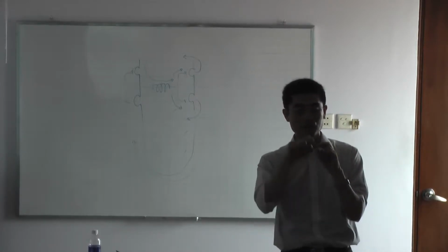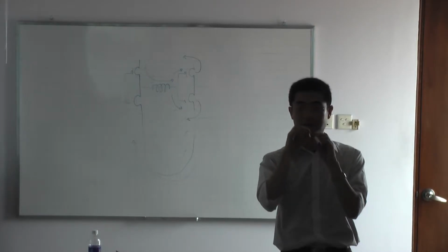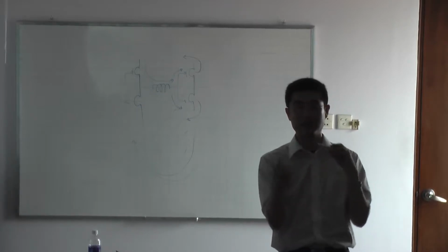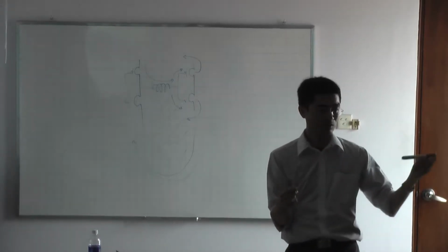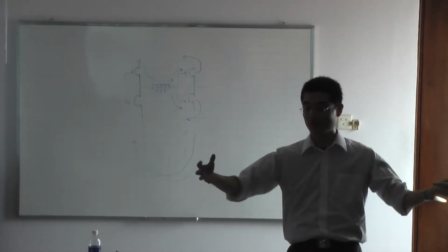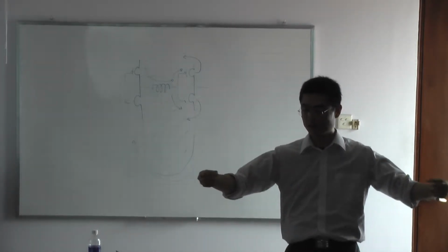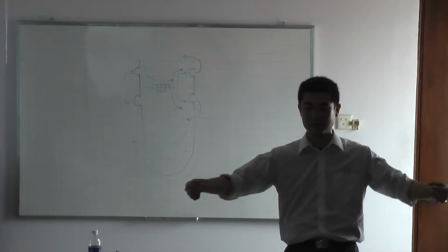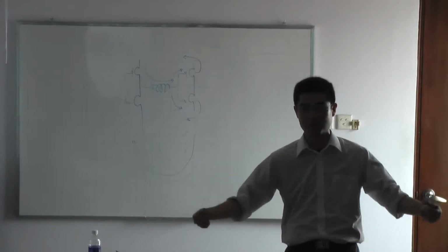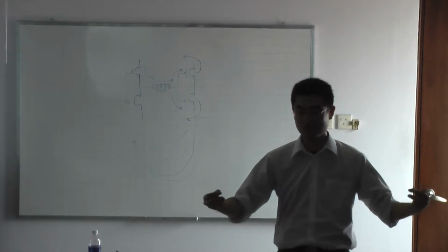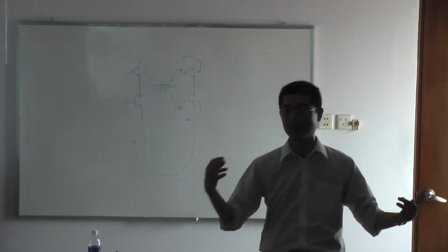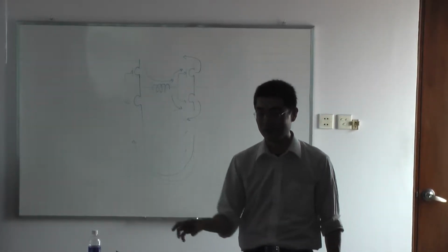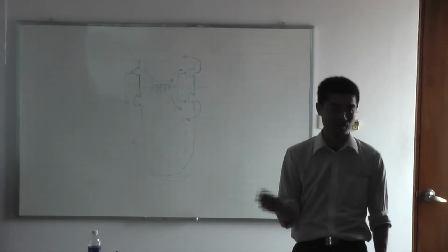So an SMA cable has two parts. One is the center line, where the signal goes, and it is surrounded by a ground line. So once you connect device A and device B, we have to care not only about the signal connections, but also about the ground connections. The SMA cable always comes with the signal and ground, so you have to take much care about the ground connections on the SMA cable.